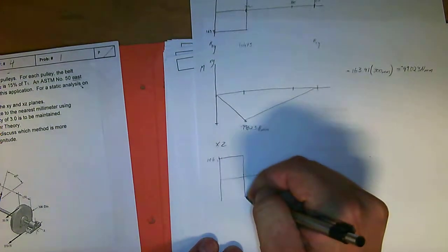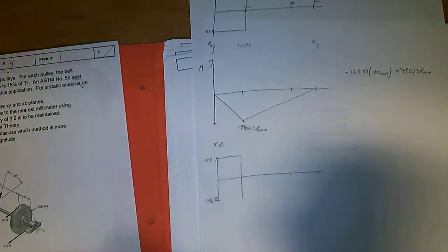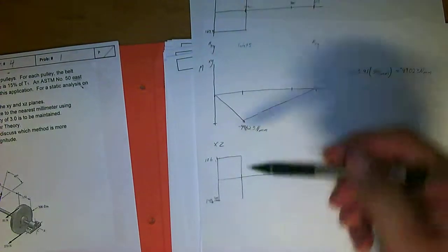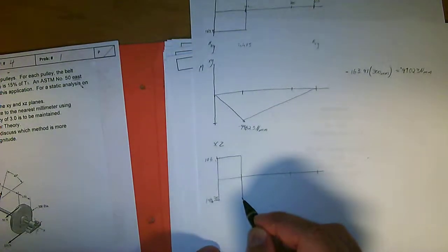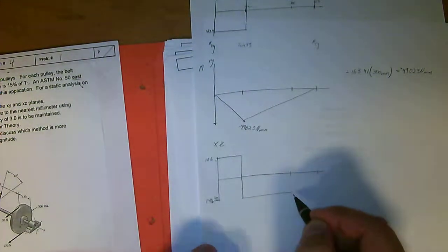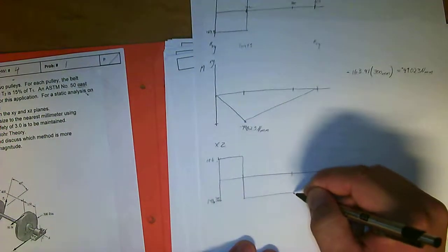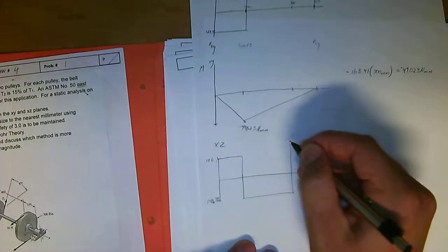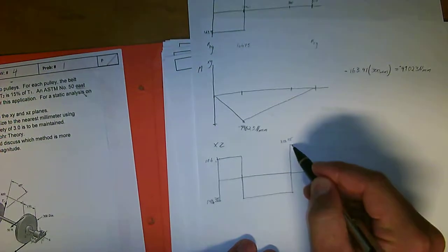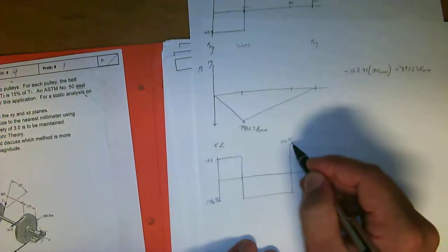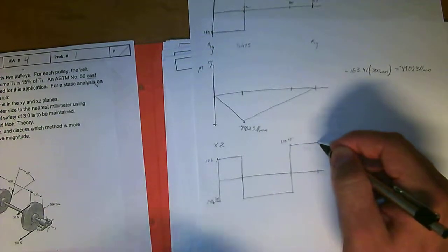146.35. I know I'm going through this kind of fast, but you can get the basic idea of what happened up here and then just apply this down here with the new reactions. And this is a really long problem, so I don't want to create a terribly long video. So then going up here again, the new force of the T, the main force on this pulley over here, comes into play and takes it way up here to 172.45. That's the addition of 140 and then 320, which is the forces on this pulley over here. And then you take that over here, and then RCZ shows up, and it takes you down pretty close to 0. It's actually off by about 1, but it's close enough to 0 to be within rounding error.